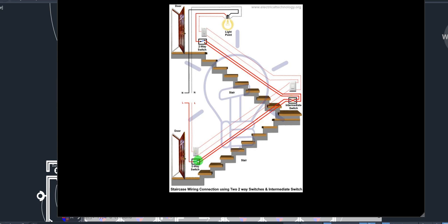Remember, this one is three terminals: common, line 1, line 2. This one has two inputs and two outputs, two incoming and two outgoing. Line 1 is coming, line 2 is by the side, then line 1 is going out, and line 2 is also going out. Input is 2 and outgoing is also 2. So that is why it has four terminals.